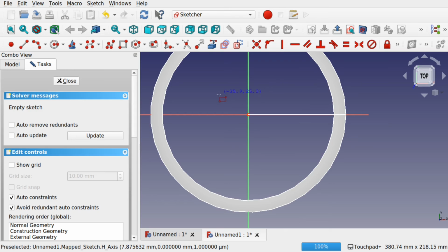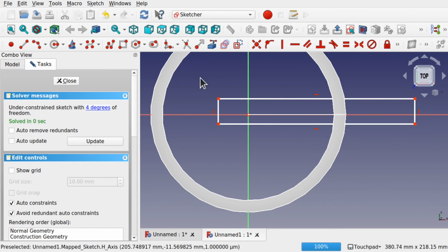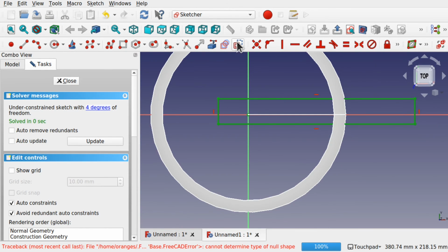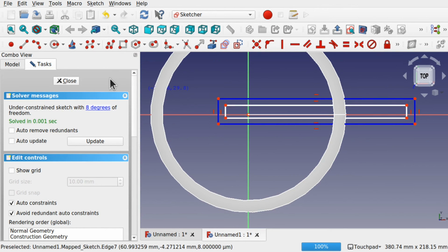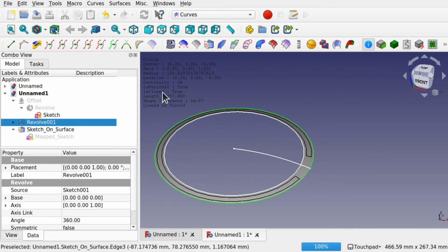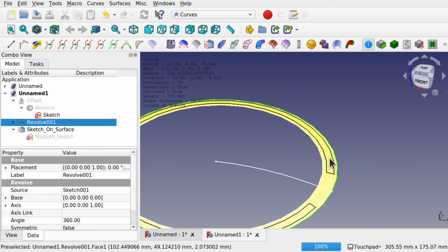And we can add our construction geometry. And we'll just put something in here for the time being, like so, and hit close. Therefore I'll get that around there, then I can take the edge, find out its length, so I can come up here, find out the length, 757, transfer that back to the sketch, and then do the same with the text, place this text upon here.